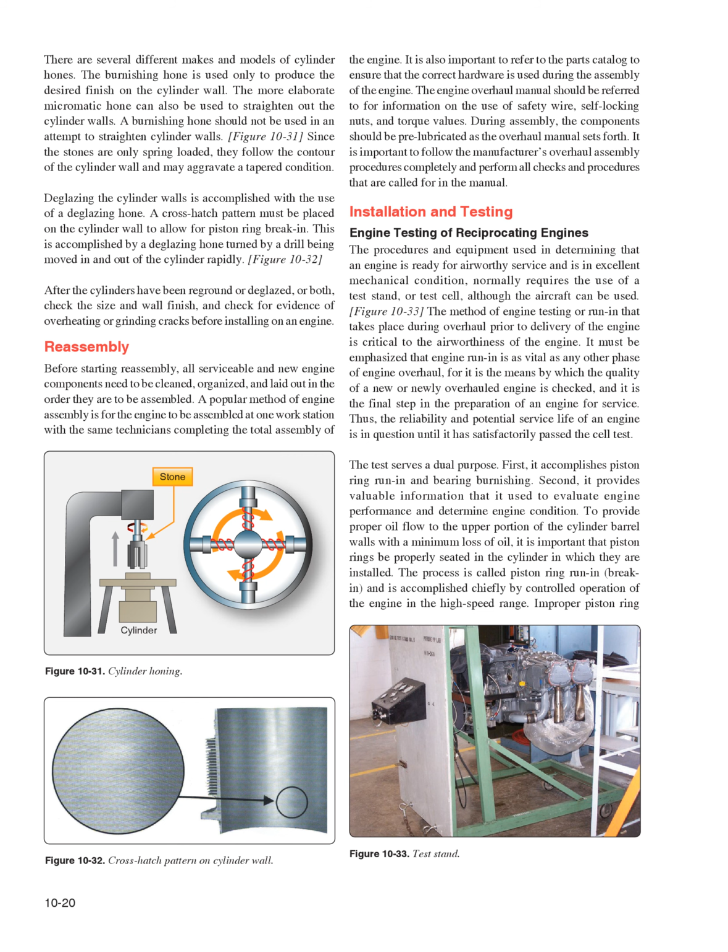During assembly, the components should be pre-lubricated as the overhaul manual sets forth. It is important to follow the manufacturer's overhaul assembly procedures completely and perform all checks and procedures that are called for in the manual. Installation and testing.